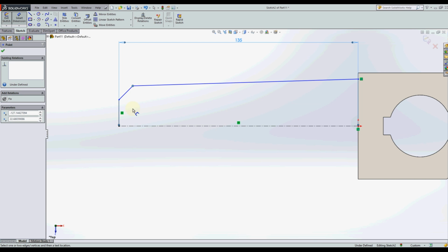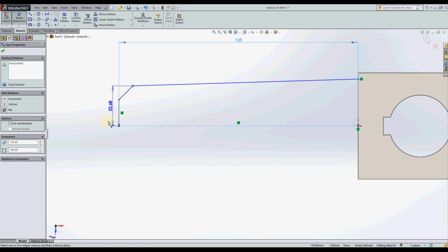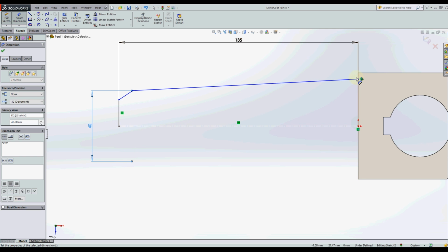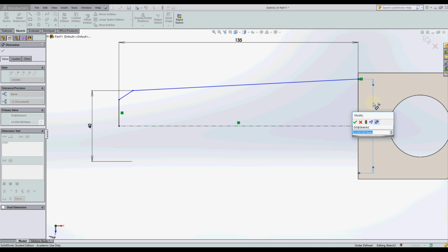The width here from this point to the center line is 20, but the complete width, as stated in the drawing, is 40. If you select the center line, SolidWorks will automatically snap between the half and the full dimension. This is because SolidWorks knows, hey, here the user has selected a center line, so he will probably be working on a mirror or a revolve. So we usually apply the full dimension, which in this case is 40. Do the same with the other edge. It automatically snaps to the full dimension because we previously showed that this is what we wanted.